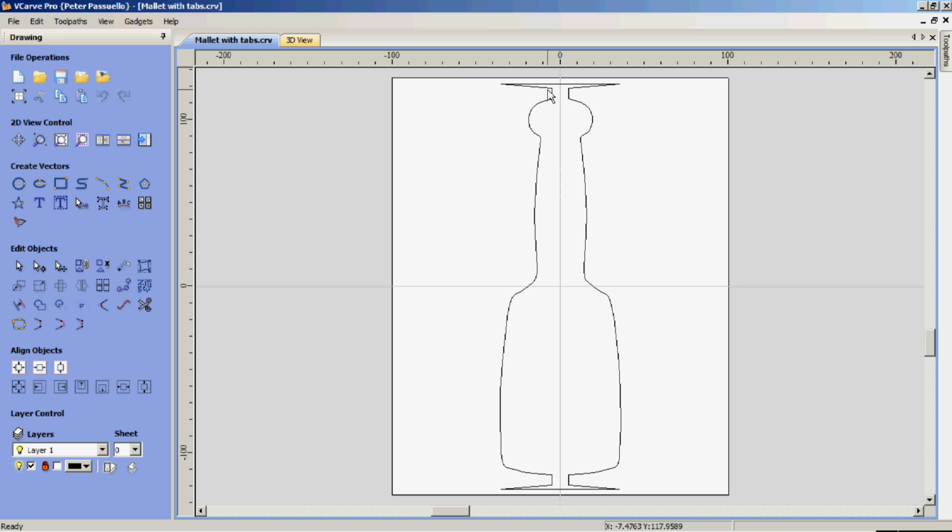So by just putting this slightly flared section on here, and I made it a 5-degree flare, it should force it to bring the cutter down in steps to get down to this final diameter here, and that's only 10 millimeters across here, so I'm going to be using basically 10 millimeters of unmachined area to hold this mallet in place, and that should be more than enough.